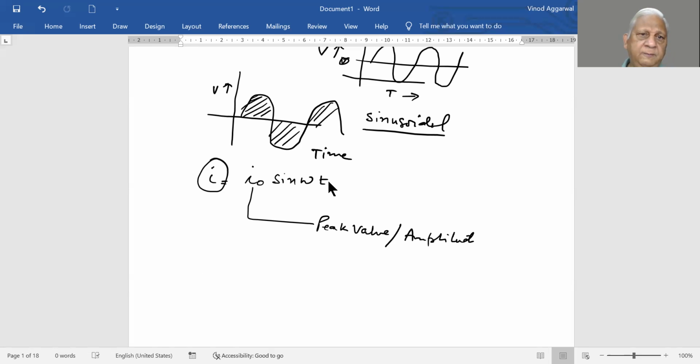Now, as we see that this voltage goes through positive cycle, negative cycle, positive cycle, negative cycle, it makes certain calculations very tedious for us to perform and to understand. For example, if you want to calculate current, heating capacity or work done, if you see the power in a bulb, then earlier in a DC current we could simply multiply current by voltage and it will give you power.